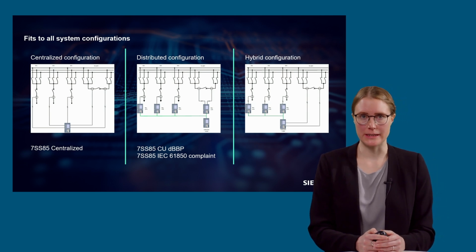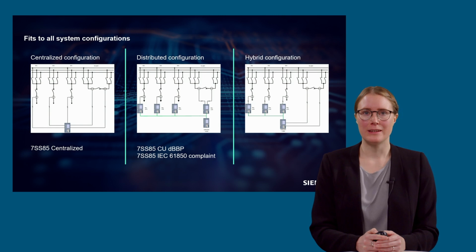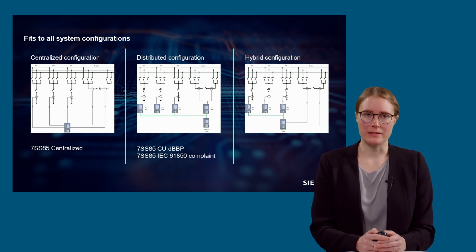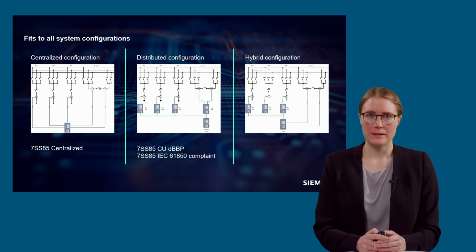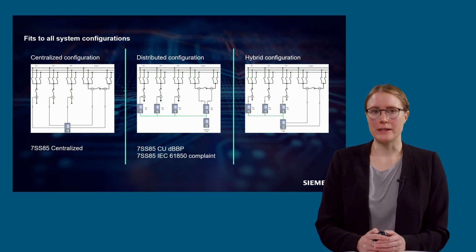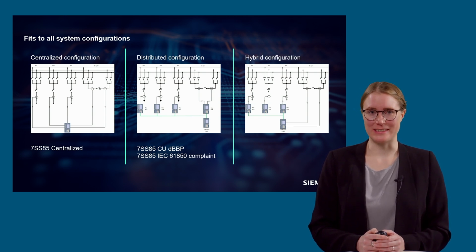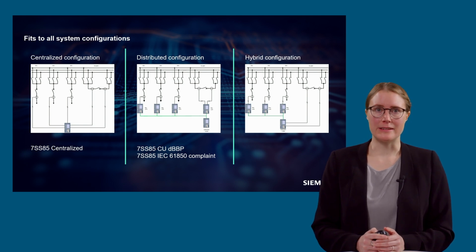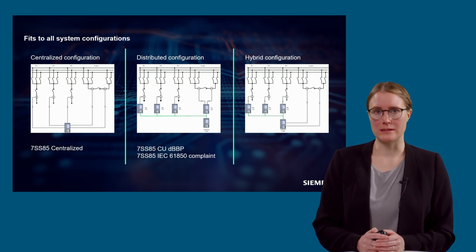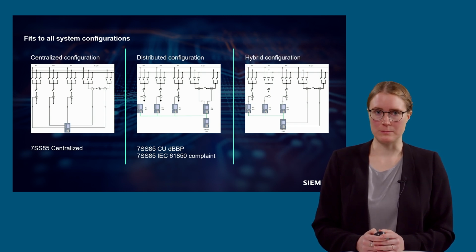The 7SS85CU distributed busbar protection solution is also a process bus solution based on the IEC 61850 protocol. There are flexible streams used, but with the fixed stream type IEC 61869-9. The sampling rate configuration is set to 4000 Hz and 1 ASDU. For the bays, only proxy elements are available. The engineering is simplified following an automated process. It is additionally possible to configure user-defined GOOSE messaging. With this solution, it is not possible to integrate third-party merging units.